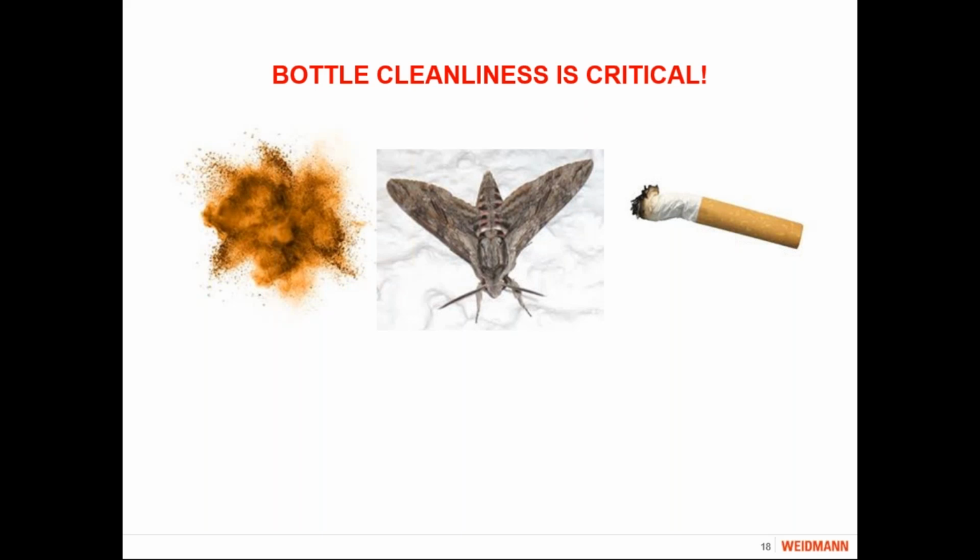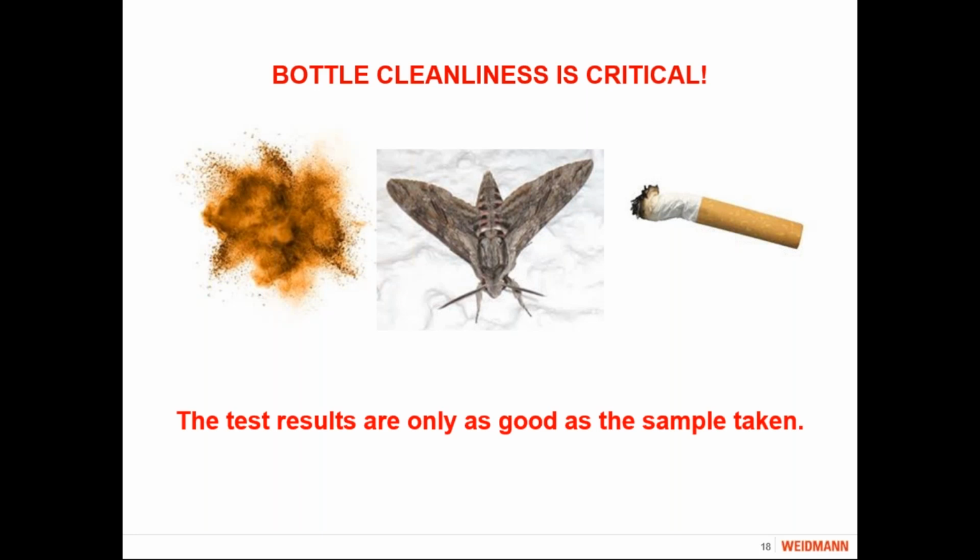Otherwise, the results you get from your tests are not going to be representative of what's inside your transformer, and you've basically wasted some time and money. The test results can only be as good as the purity of the sample taken. So if you give us a contaminated sample, you're not going to get real accurate test results. It will be accurate in the sense of that's the quality of the oil as tested, but it will not be accurate in the sense of this is the condition of the oil that's inside your transformer, and after all, that is what you're most interested in.